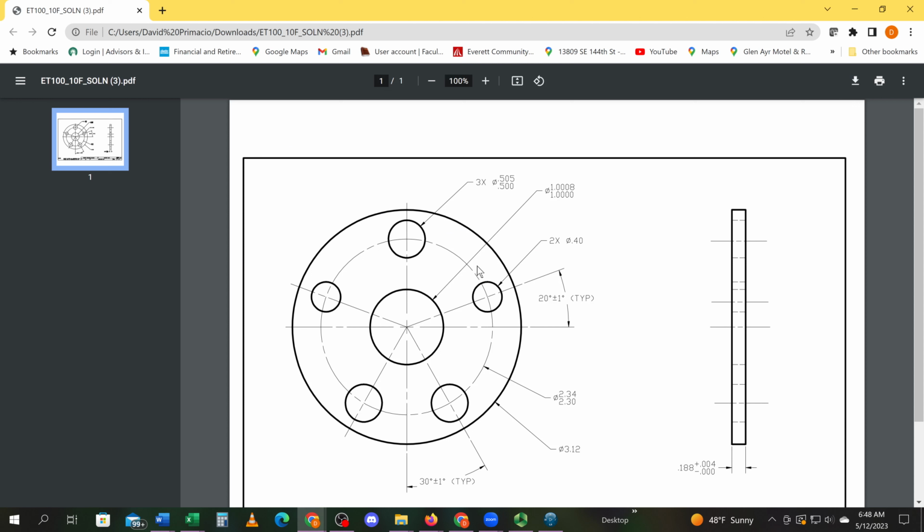The next one we'll try and create is this circle here, which is a 1/2 inch. Oh no, I'm going to create this big circle in the middle, because this is all holes right down the middle. These are all holes because I can tell these are all hidden lines. So this is a 1-inch circle.